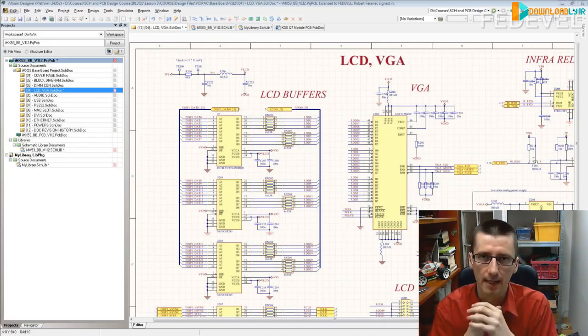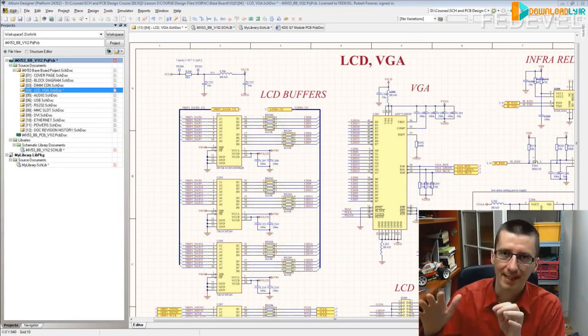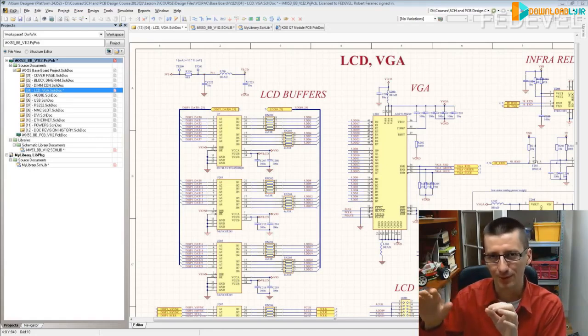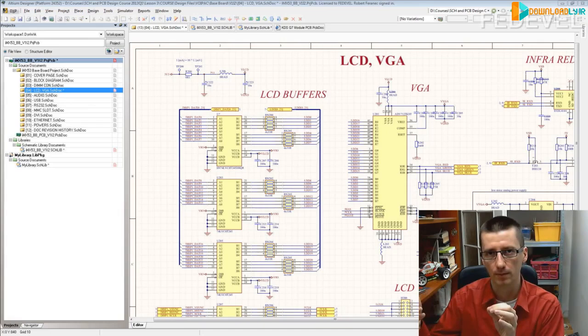In the second design, when I used only one connection, I need to say it was separated somehow, but not exactly the right way, and the analog ground was picking up noise.